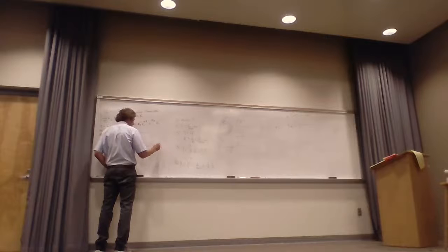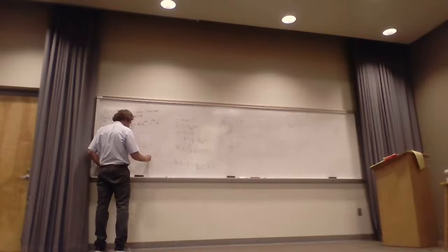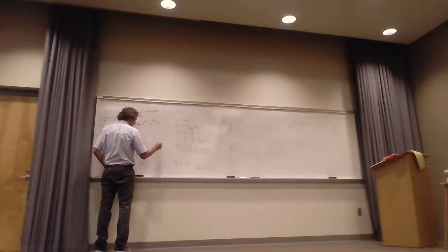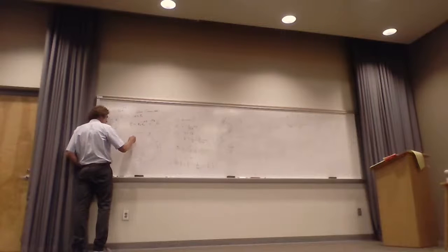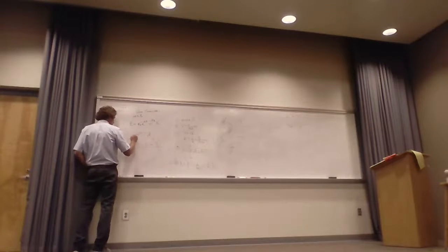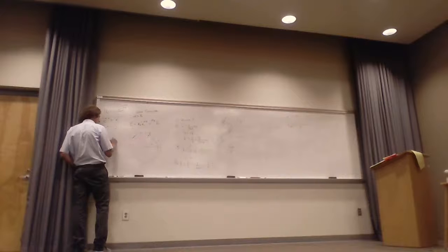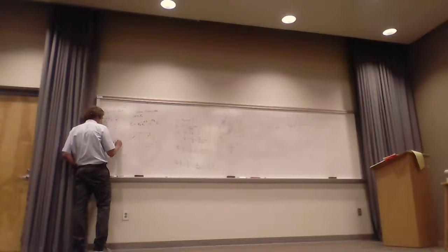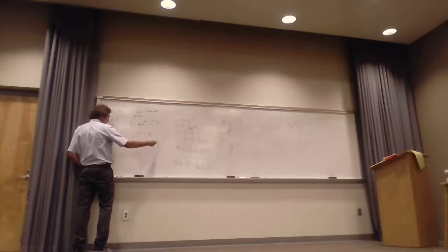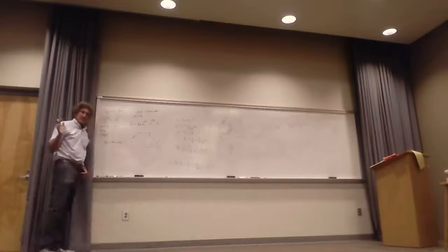If this is radius A, and this thickness is going to be a skin depth here, then this area that I'm chalking off like such would be the area of the entire wire, or pi A squared, minus the area of this internal portion, or minus pi times A minus the skin depth squared. Does that make sense to everybody?